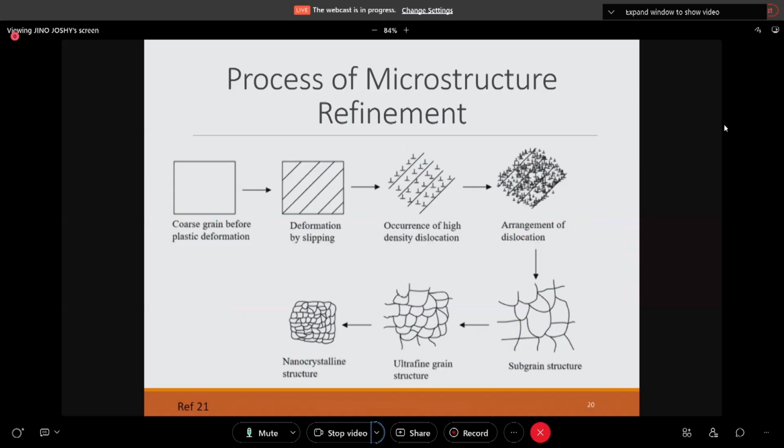As this process is continuous, dislocation multiplication can happen, and thin shear bands or thin stacking faults also form on the material. This process keeps on continuing. Annihilation of these dislocations or defects will happen, and there will also be micro and nano cell formation, with subgrain and grain boundary formation. As this new grain boundary formation happens, it will very much affect the corrosion properties of the material.